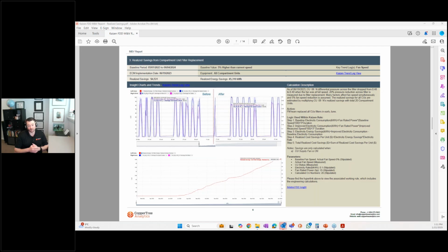To give you an example, if we open everything up fully wide and create a full airflow situation, and the sequence says that fans or pumps will run at a certain lead-lag method, and when the first one reaches 90%, the second one's going to kick on, and it will run until you get back to a delta pressure of X, and then it'll shut off and go back to standby. We can exercise that whole thing and see if that's really happening, because a lot of times we see those things don't happen, right? We have a fan that ends up running at 100% and the second one never kicks on. Things like that. So we can definitely pseudo exercise the sequences on the primary equipment.